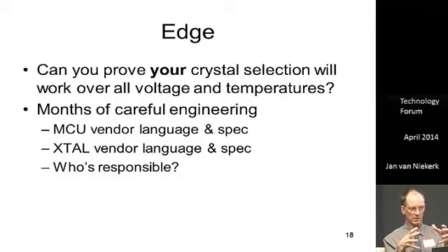So the process skew from the microcontrollers and temperature, and also variance in the crystals. You might get a batch of crystals from the vendor, and the next batch, the series resistance, unknown to you, is 10% higher than the first batch that you got when you qualified these. So it's an absolute trap that you have to be very careful of.